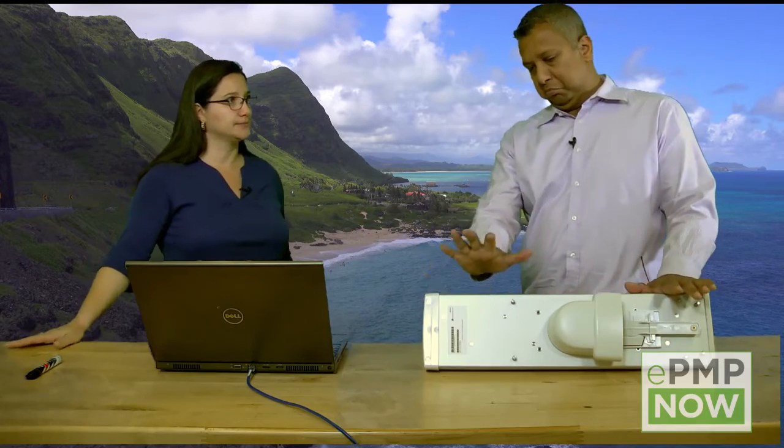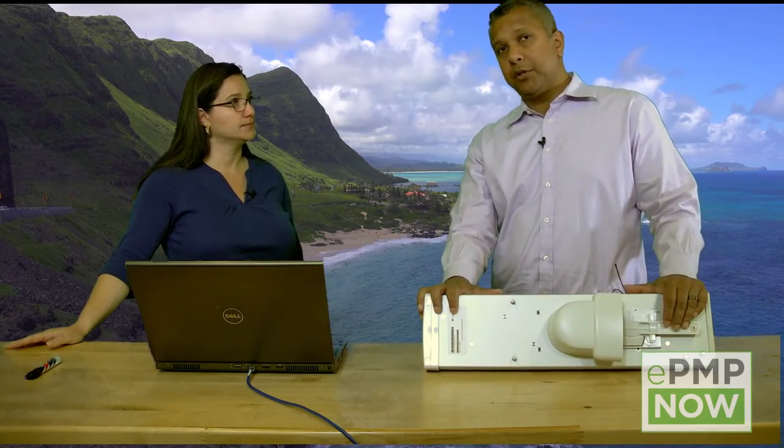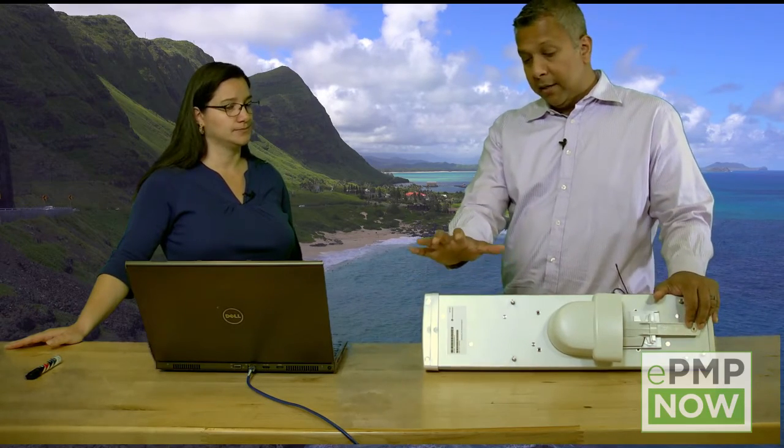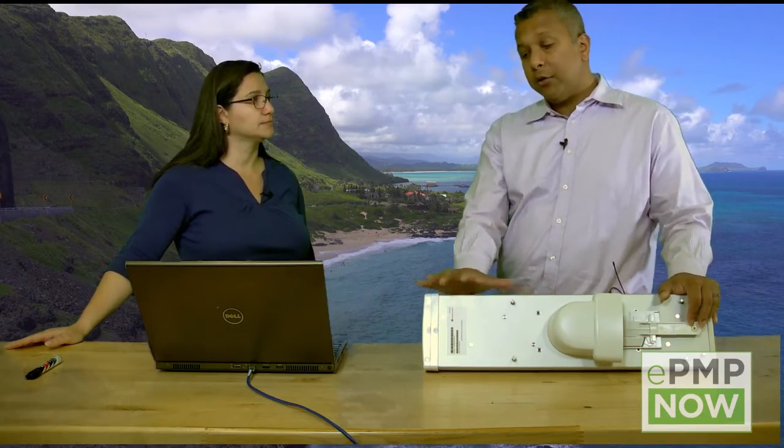But in summary, for frequency reuse in 90-degree sectors, this is a perfectly good antenna. Yes. And there is no detrimental effect of using this in a frequency reuse environment. Correct. And if you want to use this also in situations where you want to cover a 120-degree sector, it's a great antenna. Yes. But at a 120-degree deployment, you would not want to do frequency reuse. Or if you do, you may have some interference. Well, it depends where you're using the frequency.